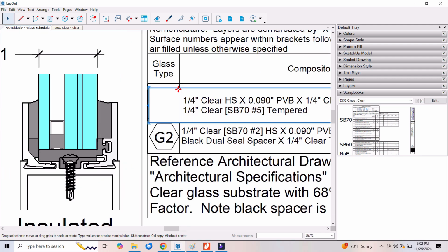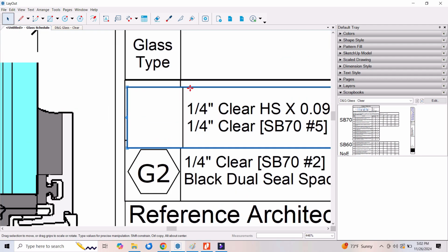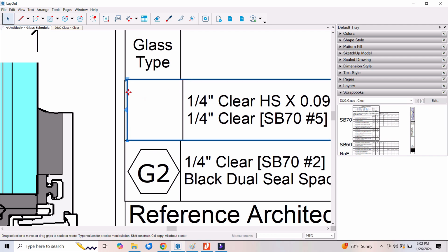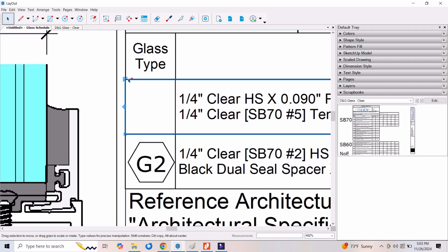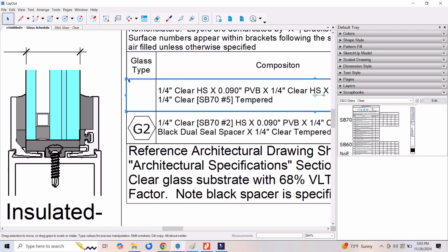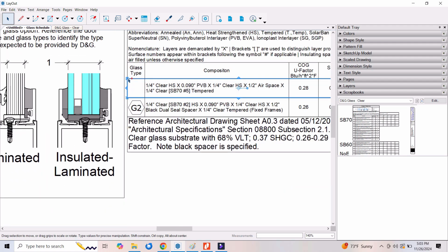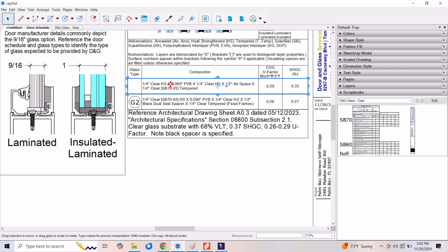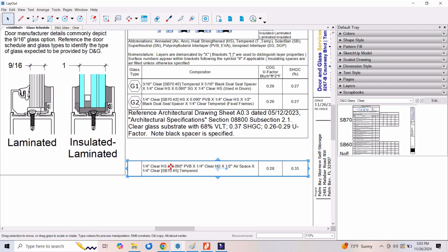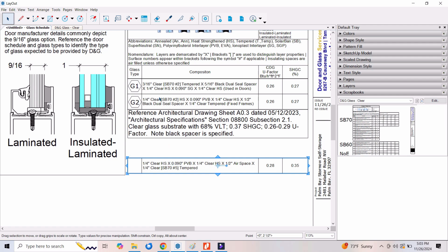Notice I have to come in here, it's tough. You want it to snap to where it goes, or lines up. So I just snapped it, right? Now you can take this, click, hold, drag, let's see, I'm going to type 0, comma, 2.5. Okay, so that moved 2.5 inches.